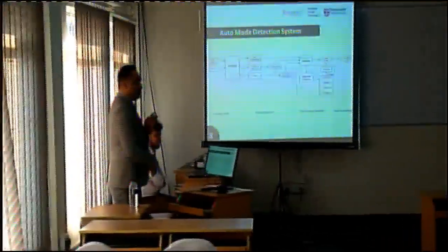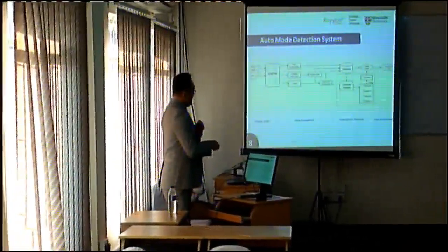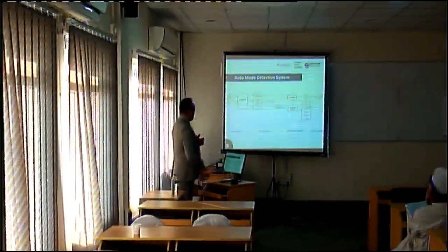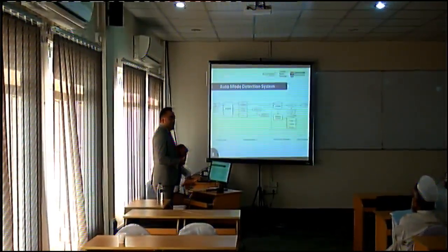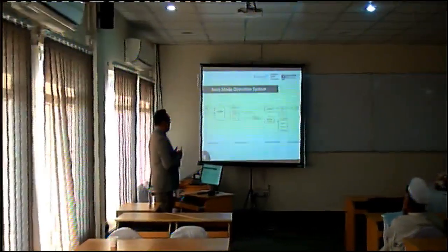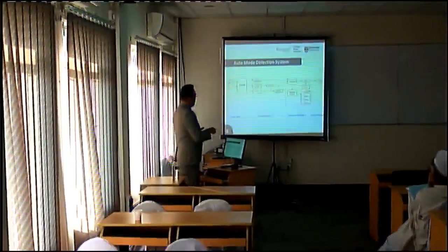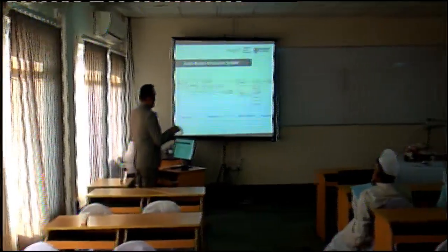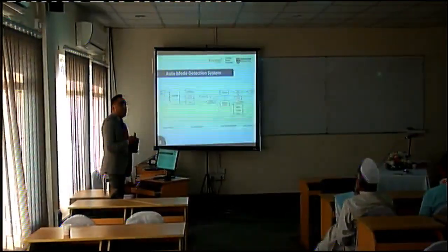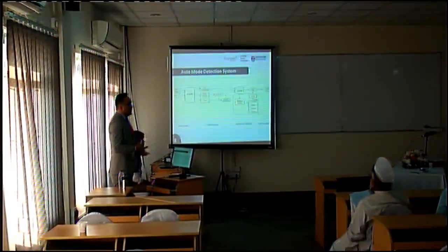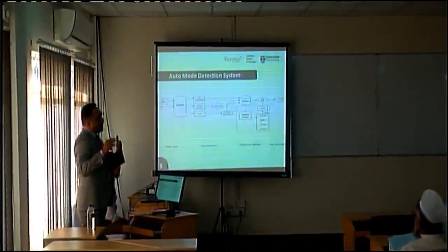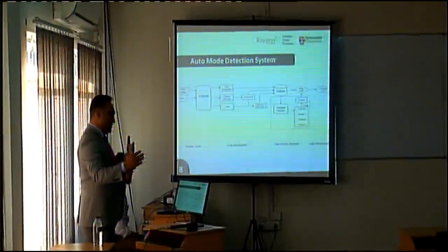You remember, it is the same data analytic model. This is the sensor data. We get the data from the fuel consumption flow meter, speed over the ground, all real-time data coming every minute. With every-minute data, we expect around 1,440 samples each day. This is the acquisition, where we capture those data. And this is the statistical model we developed. We create a mode profile for each individual mode, so when the real-time data matches a mode profile, it detects the mode automatically. After that, it analyzes the data and sends an automatic report every day.